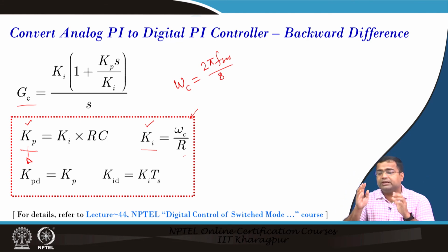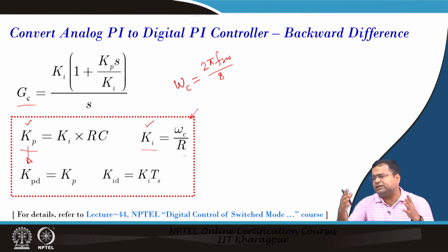Because the digital control, if you look at the small signal based design compared to the continuous time control, actually gives rise to additional delay. So, the digital control may not be a useful solution if you go by small signal design, but the digital platform offers you the ability to change the controller gain based on the operating point. That is the only advantage, and adaptive dead time. But unless you implement some more advanced logic, this digital control may not be so useful, and that is why the majority of commercial products are going with some nonlinear or other large signal based design, where you can actually capitalize on the digital controller, and you can also introduce some tuning as well as advanced algorithms.